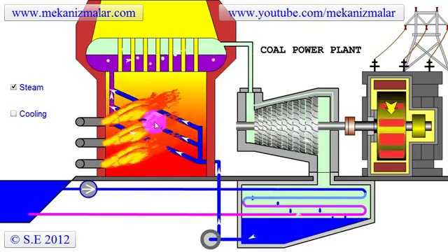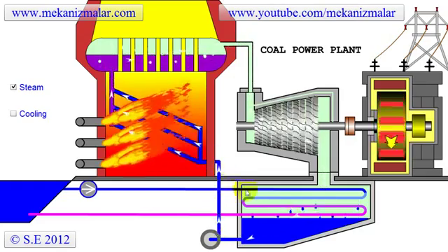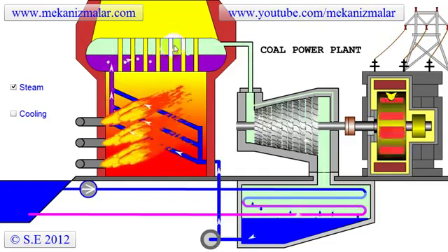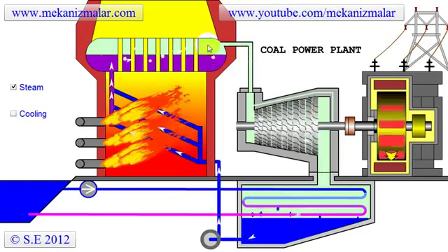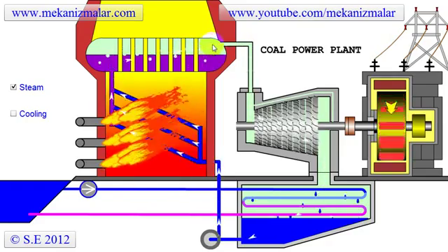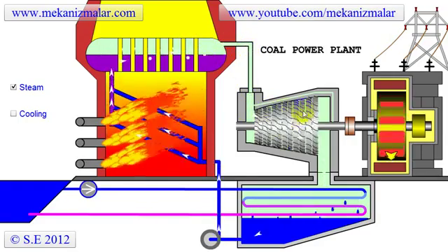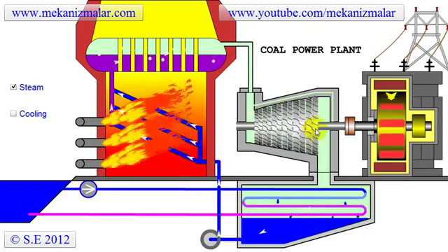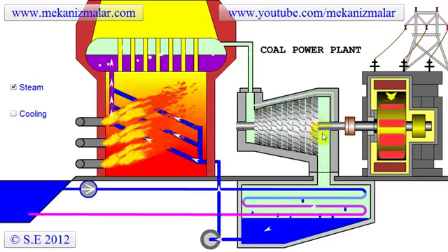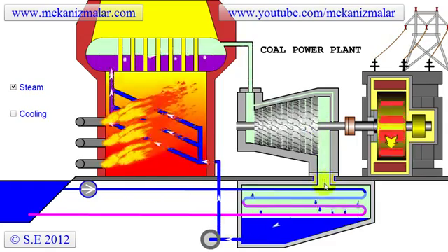First, intense heat inside the furnace heats the water within the coils, which is coming from the condenser. This heated water is forced to the boiler, where it evaporates. The pressure inside the boiler can be more than 200 bars. The high-pressure steam obtained in the boiler is sent to the steam turbine, which passes the steam between fixed and rotating sections, converting the energy stored in the steam to mechanical energy. The steam leaves the turbine at close to vacuum pressure, near condensation temperature.